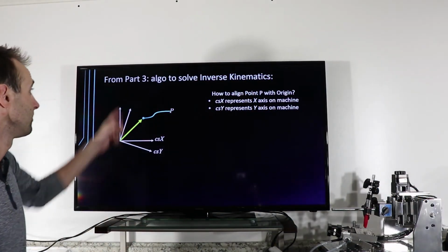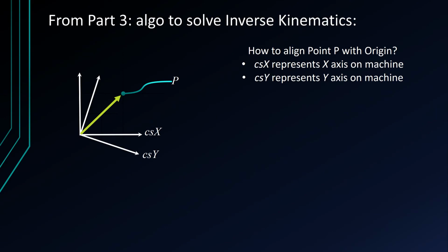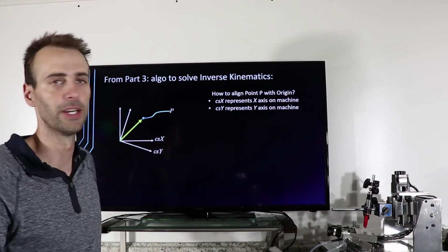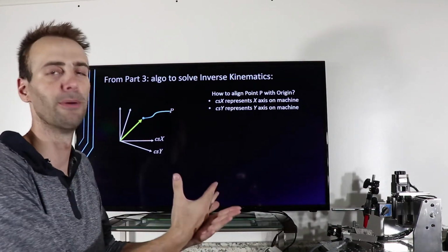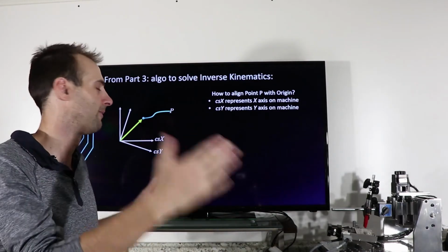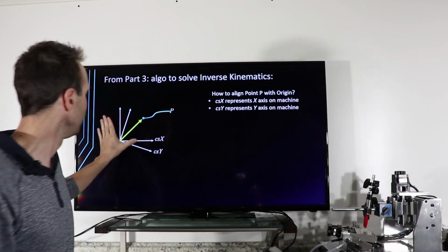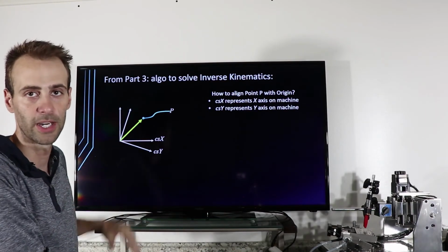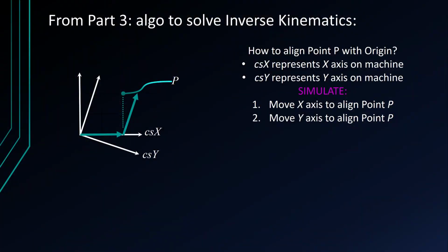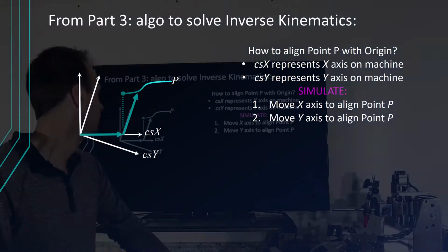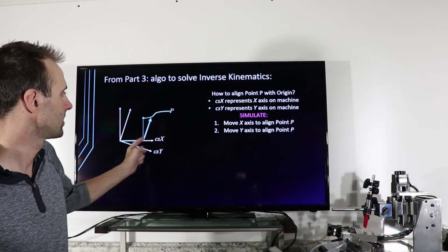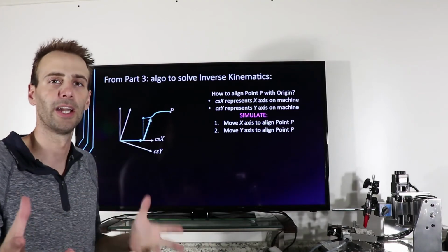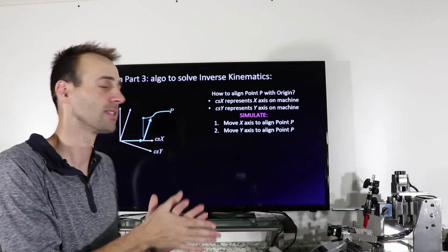So just as a refresher from part 3, the goal here is to get our machine to drive to this part location, right? Maybe from here, from 0, 0. If it's from the homing position to the first point, we have to go from here to here. But now remember, our x-axis and y-axis in this case had a squareness error of 45 degrees or something like that. So what we have to do, if we moved the x-axis and y-axis by that part coordinate, we would miss by some amount, depending on how bad the squareness error was, right?